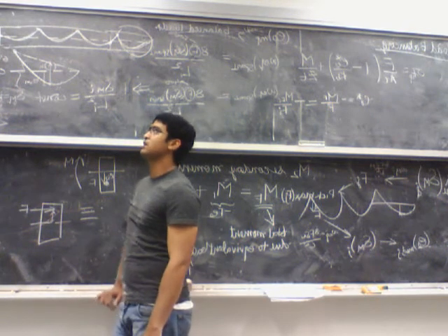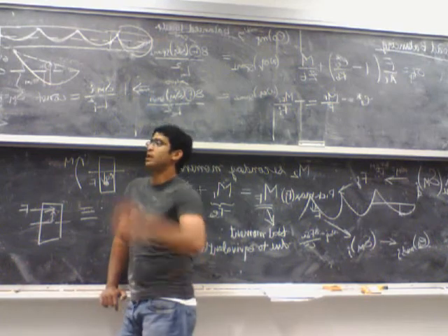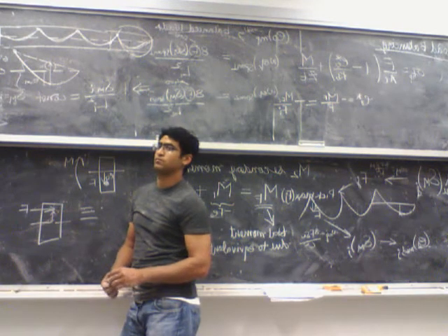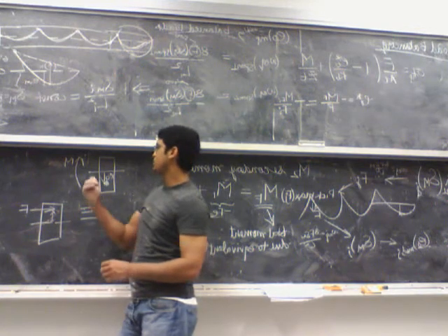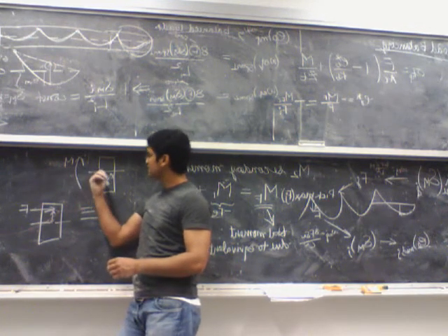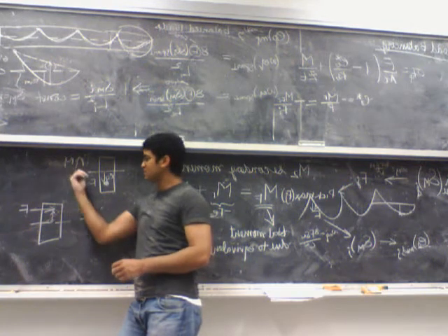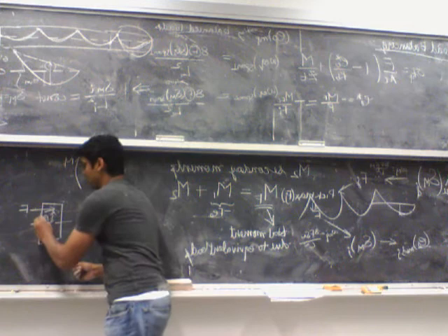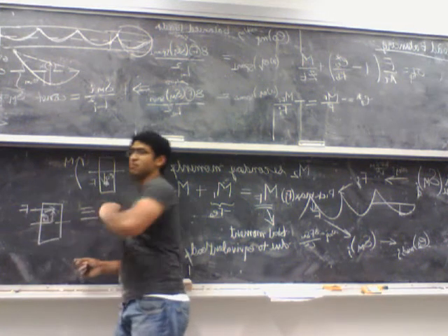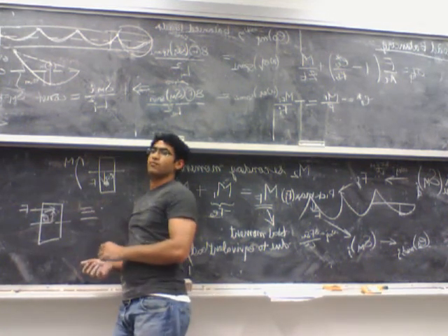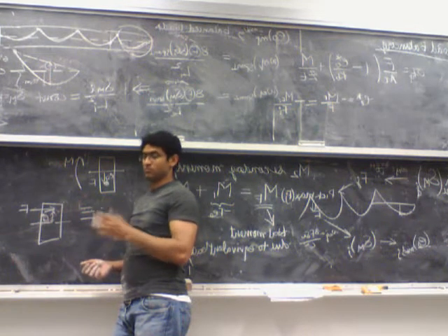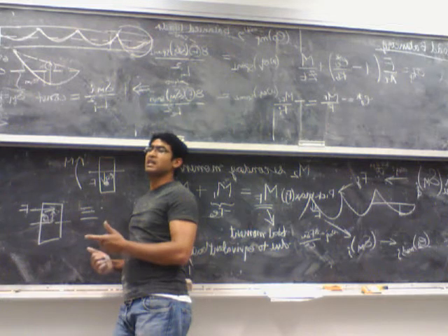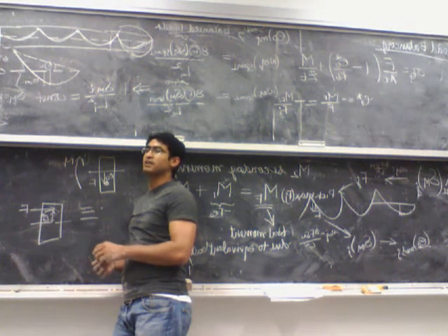So that thrust line gives you the location of the equivalent compressive force on the cross section. So the stress produced by the pre-stressing force at e naught and the external moment in this case is the same as the stresses produced by this case where this is F and this is simply e naught star. Is the C line in a determinate beam the same as the thrust line in indeterminate beams?